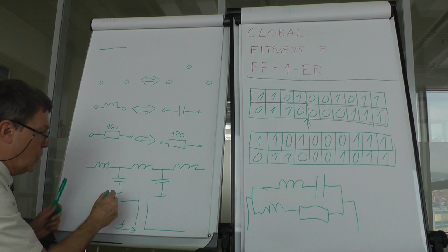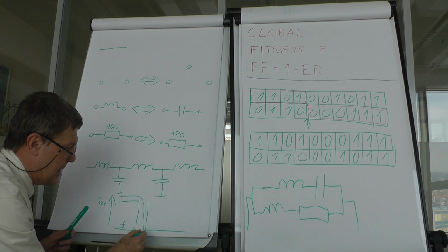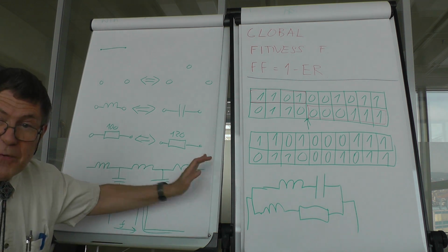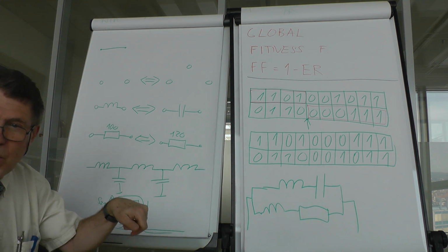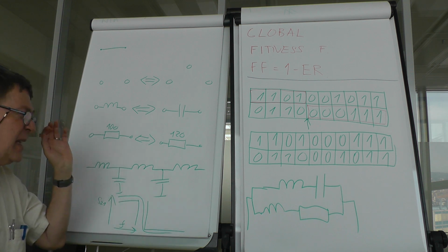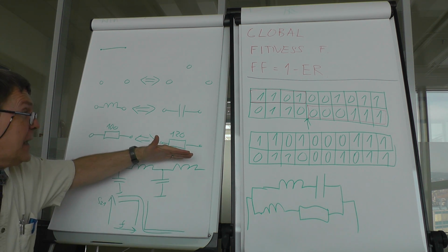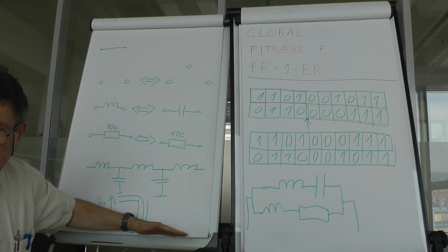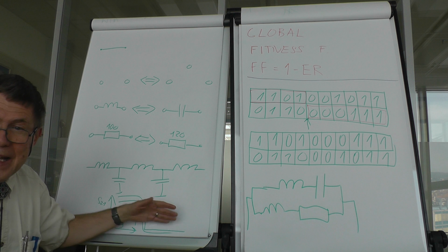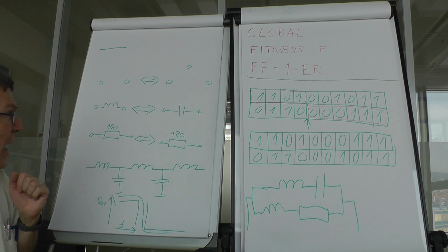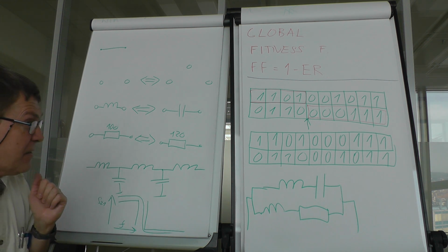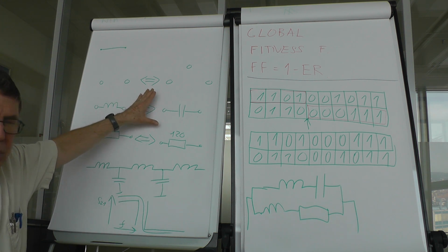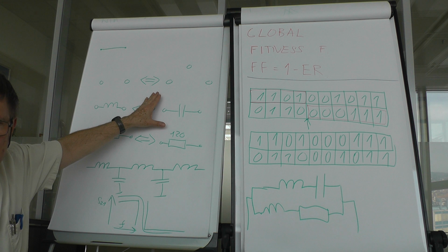So if you want to get a filter which looks like this, you can get an optimum solution using circuit theory for Butterworth, Chebyshev, and other types of filters that have additional properties like minimum phase change, minimum group delay, or other important design criteria. And running this algorithm will not give you those optimum filters.